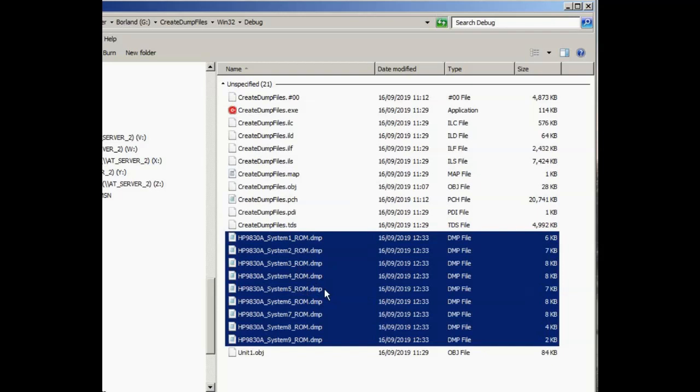In which case, of course, the next step is to get the replacement ROM card made up and get the firmware from the emulator programmed in and see if that brings the machine to life at all.